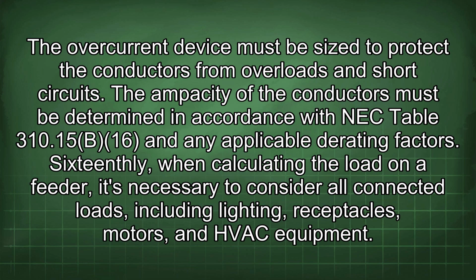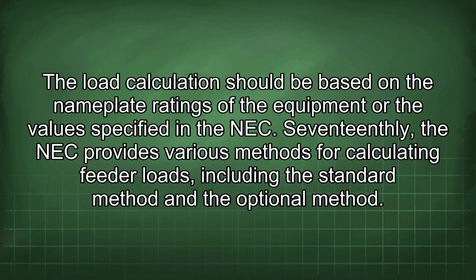16thly, when calculating the load on a feeder, it's necessary to consider all connected loads, including lighting, receptacles, motors, and HVAC equipment. The load calculation should be based on the nameplate ratings of the equipment or the values specified in the NEC. 17thly, the NEC provides various methods for calculating feeder loads, including the standard method and the optional method.